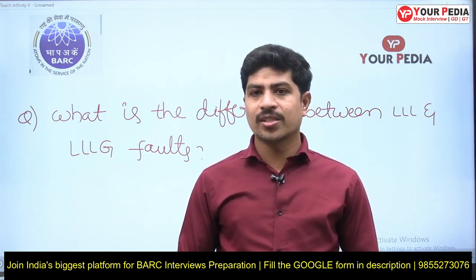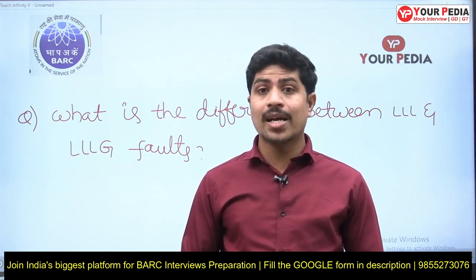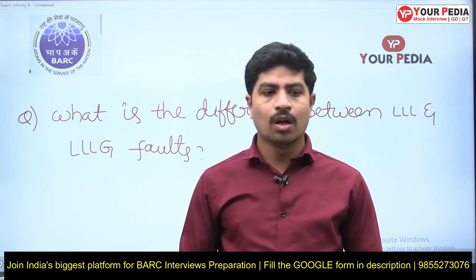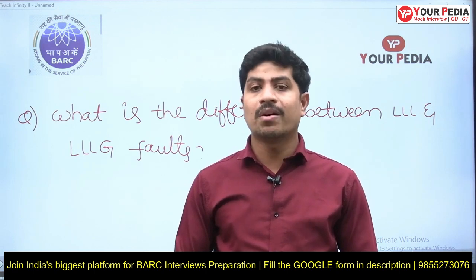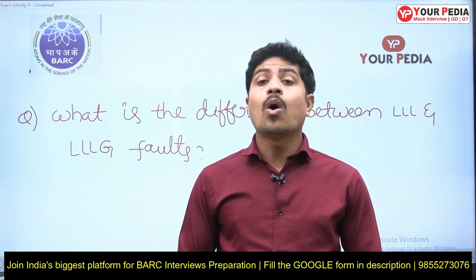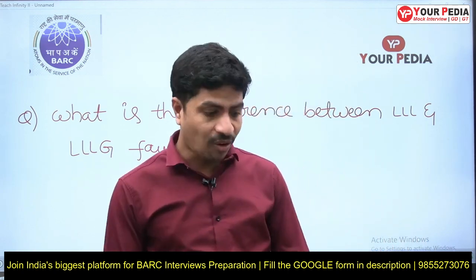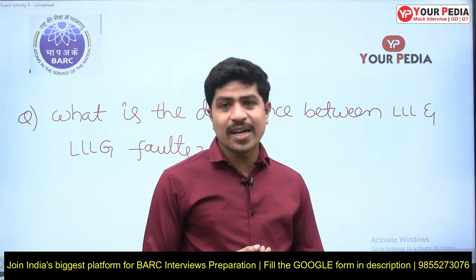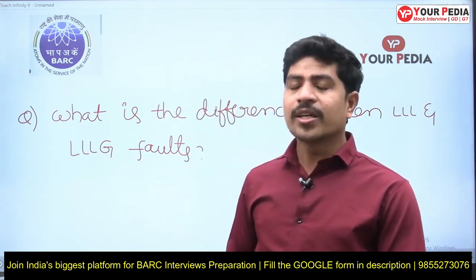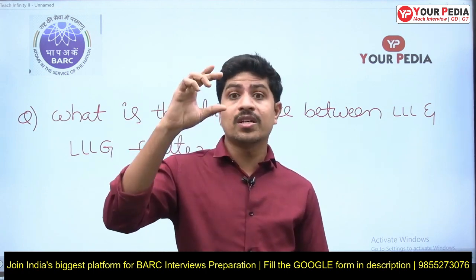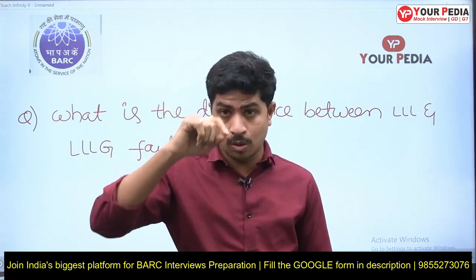Today I am going to discuss one of the interview questions that was asked previously in Bhabha Atomic Research Center interview for one of the students, from power systems. That is, what is the difference between three-phase fault, LLL and LLG fault? Immediately students will say that yes sir, in LLL fault all three phases are shorted, but in LLG fault all three phases are shorted and that is connected to ground also.